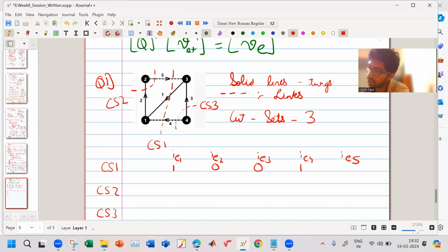So what I recommend is that you assume I have made a cut set over here, and I've assumed 1 is going out. That is to the left of the cut set I have given. So this arrow also should be at the left of the cut set. This arrow is already to the left of the cut set, and this arrow is already to the left of the cut set. So all the arrows should be at one side of the cut set.